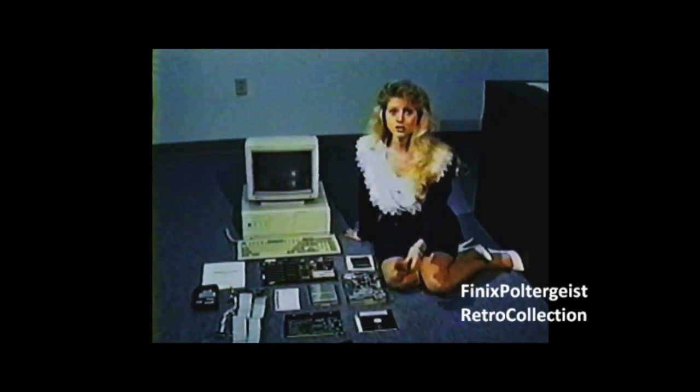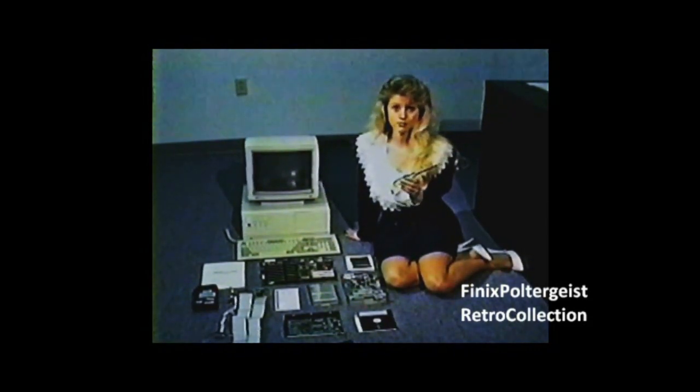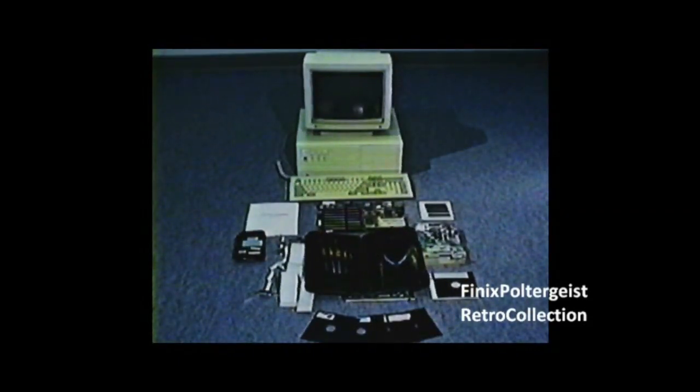The only tool you'll need is a Phillips head screwdriver. However, a small computer toolkit can come in handy, especially when you need a pickup tool to retrieve a screw that has dropped into a tight spot on the motherboard. All necessary hardware comes packaged with the case. Necessary documentation comes with each manufacturer's component and is also provided in your technical starter kit. Your work area should be clean and should provide enough space for you to organize your components and hardware.